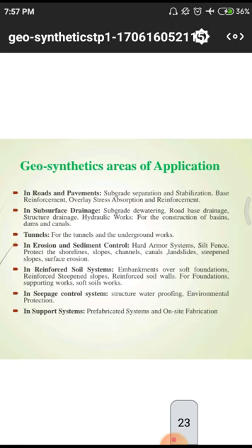Because there is penetration of water and different separations, so in roads and pavements we have to observe this kind of application of geosynthetics. First, subgrade separation and stabilization, base reinforcement, overlay stress absorption, and reinforcement. In all those conditions we have to utilize these properties of geomembranes and geotextiles.